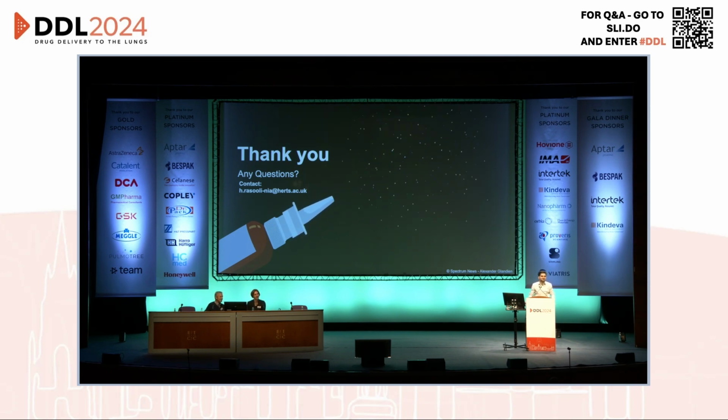So I'm interested in the time dependence. You mentioned that you had a static inlet velocity, and you input the Cross and the power law models, but you didn't include any thixotropy, any time dependence to the shear rate changes. So when you actuate a nasal device, I guess there's some change in the velocity and the stresses in the device as you're pressing it. Is that right? And I just wonder if you were to include those things, would you see a difference?